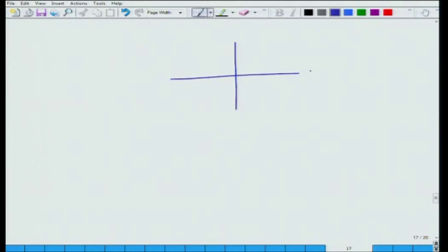What we have is, if I get too close to -1, 0, this is the G open loop j omega. If I pass through -1, 0, I have sustained oscillations. If I encircle -1, 0, I have instability.